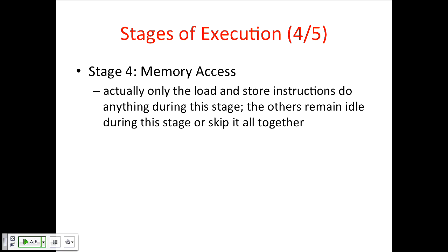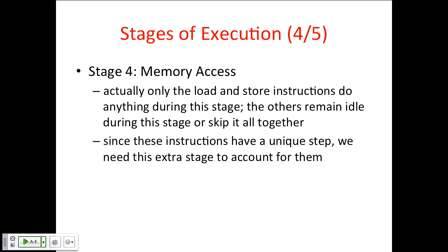The fourth stage is memory access. Obviously, this is only done by instructions that access memory. In the MIPS, those are only load and store instructions, right? All the other instructions just do nothing during this phase. This is only for the loads and stores. All the other instructions don't have to worry about this stage, just loads and stores.